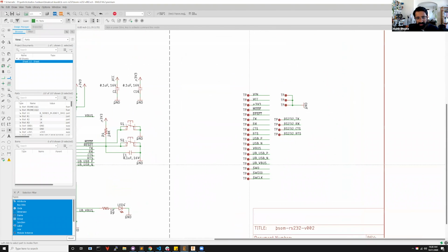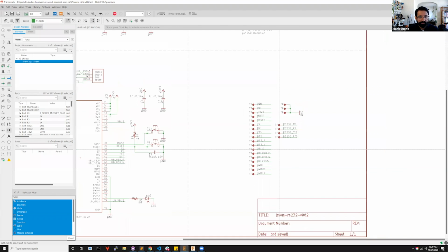And last but not least are test points. Sprinkle as many test points as you can all throughout the board. The future you will be very thankful to you. This will also help us during manufacturing. If you wanted to do an automated test fixture, these test points can be used to make sure that your device passes assembly, or if you wanted to load up new firmware post-assembly.